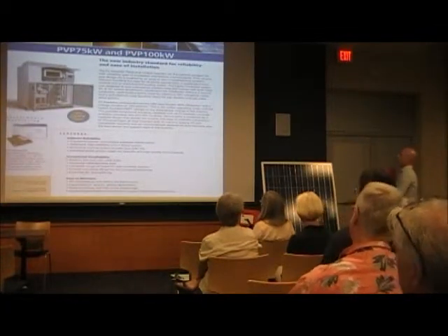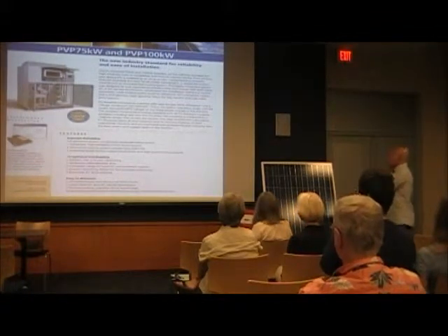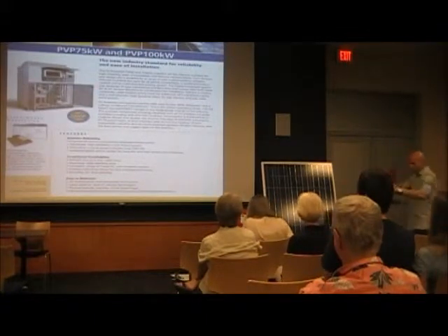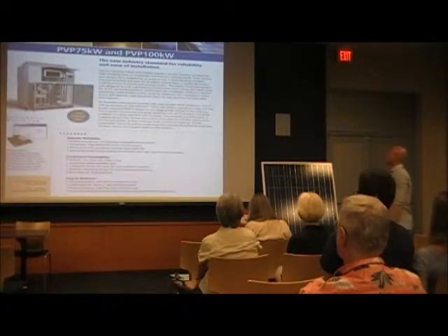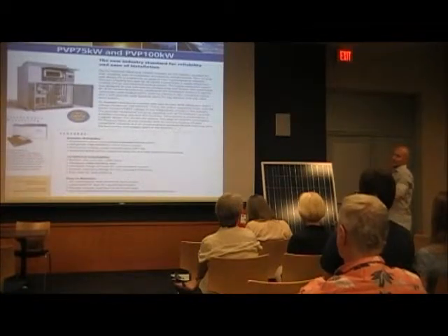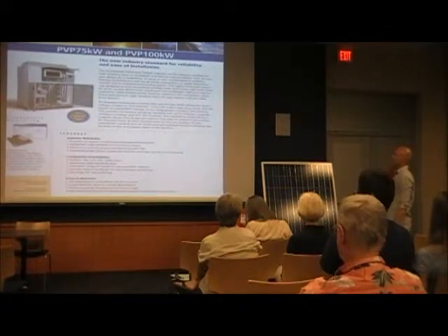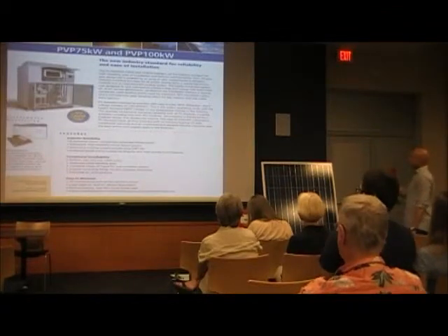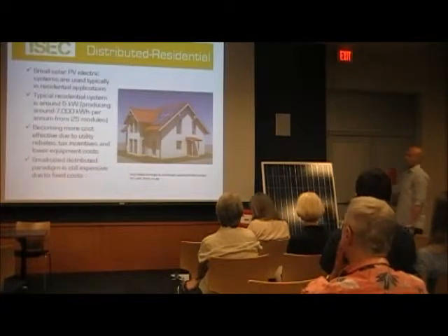They try to mitigate a lot of risks on this, where they have what they call card cages, where if one goes down, all they do is pull out the card cage and put a new one in. The changeover is really, really fast. Real reliable. We've had inverters changing from AC to DC, DC to AC throughout the last 40, 50 years, so inverting energy is not really new to the game. They have 10-year warranties on them, and you can buy an extension of 20 years. We usually see the inverter go out at about 15 years.